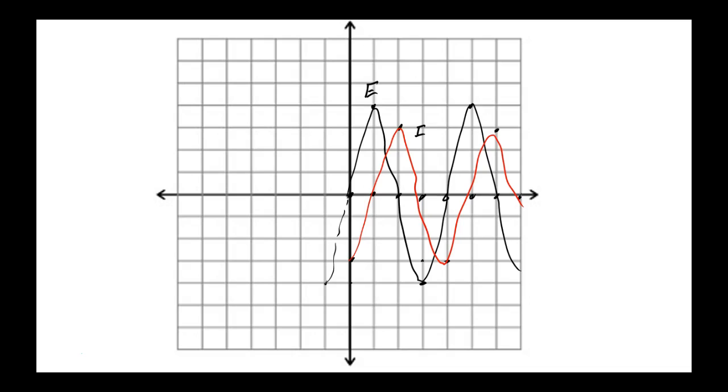Now, I said before, there's another word coming up that sounds like it means the same thing as two other words. And that word is impedance. It's a measure of the total opposition to current flow. Okay? In a resistor, the opposition is called resistance. Okay? In an inductor, it's called reactance. It's reacting to the current flow. When you combine the two of them together, it's called impedance. It's impeding the current flow. So, yeah, that's why it's so hard to keep up with which is which.